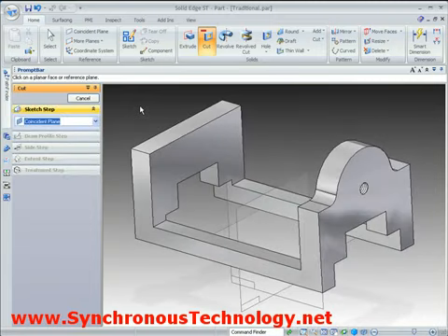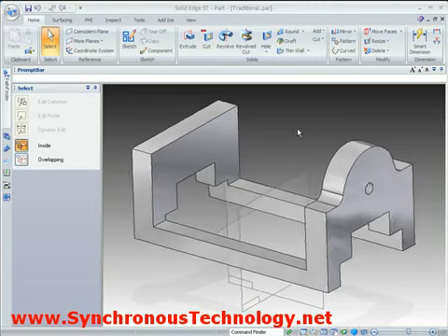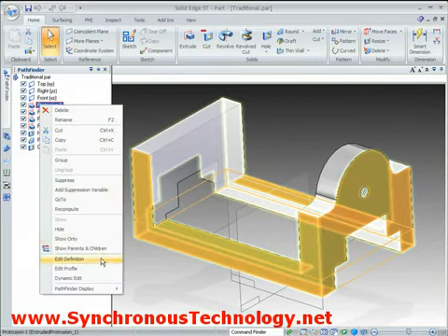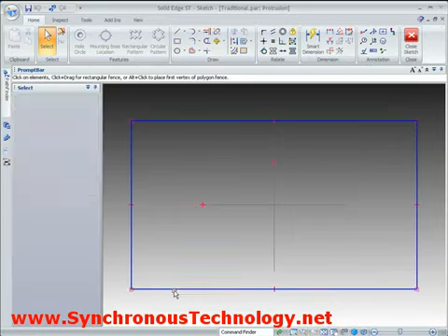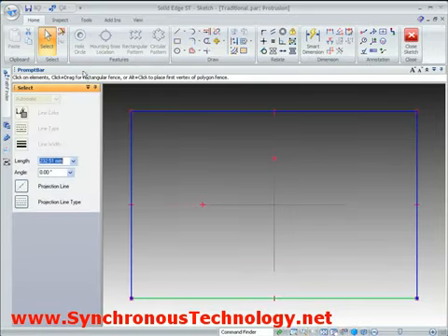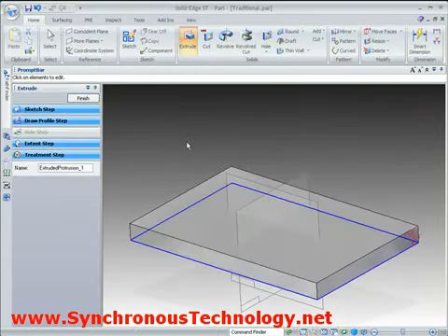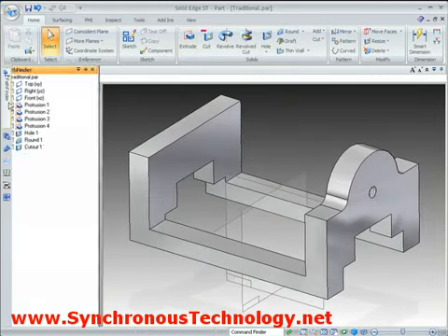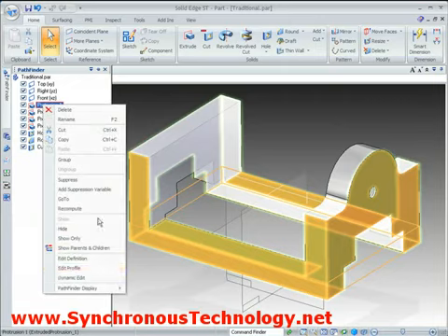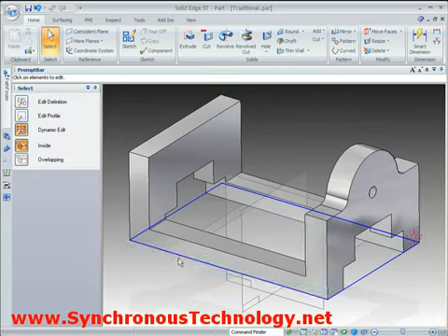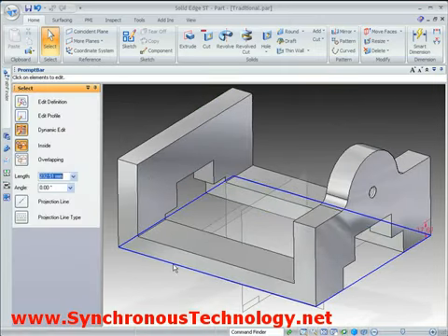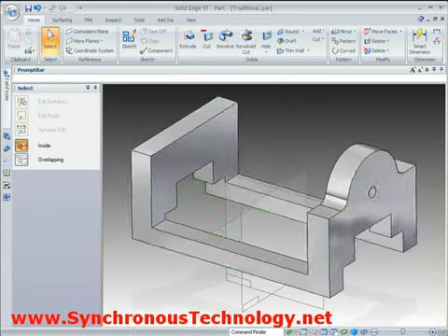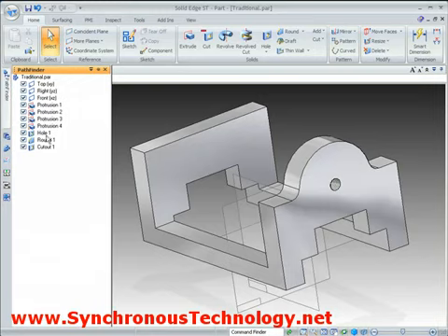If we find we need to make edits to the geometry we've created, in a traditional history-based modeler, this involves having to adjust the underlying profiles that control the geometry. We can either do this directly in the profile, as we can see here, or alternatively, we can do it dynamically, as we're going to see now. Either way, these changes involve the model's history having to recompute. Not a problem on this simple part, but will definitely be a problem on a more complex part.